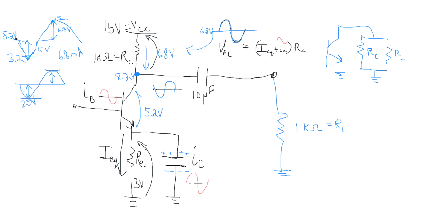We have just squashed our gain. And in fact, if you look at the AC model, our gain is proportional to RC in parallel with RL. It's a very simple formula. We have defined something called the AC emitter resistance, little re. I'm going to define it here.